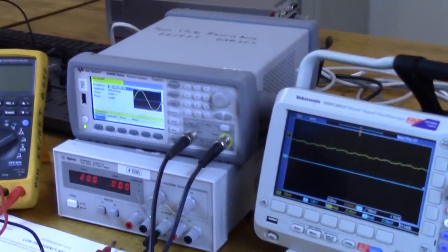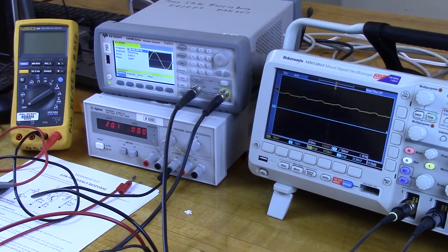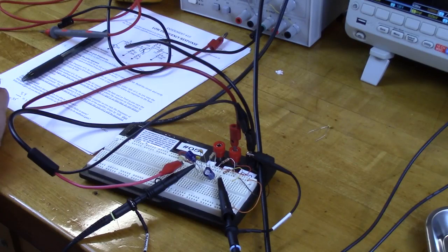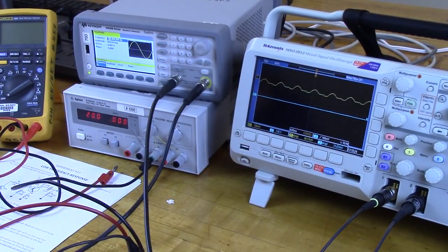So that pretty much does it for this lab. Low frequency poles are difficult to measure. Next week, we're going to be doing high frequency poles, and those are much easier to measure. Because we'd like to have a better bandwidth, we're going to replace all of these 1 microfarad capacitors in the circuit with a higher value, so that mid-band does go down to about 1 kilohertz. Next week's lab is very quick. It's just 2 frequency measurements and it's done. This is a more difficult lab. This has always been a difficult lab, but I hope you'll be able to make sense of it.